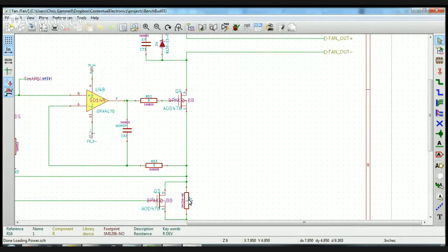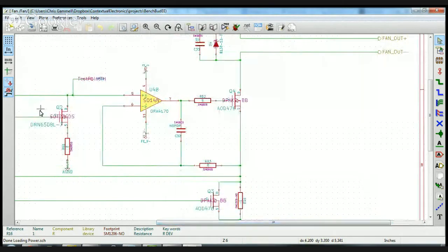So if we went to a 1/4 ohm instead of an ohm, then 4 volts would be 1 amp through here, and then 2 amps. Basically, if we start going lower and lower on the resistor here, we should get more fine control in terms of steps, because then it would be like an 8-to-1 mapping, right? So if this is now 0.125 ohms instead of 1 ohm, we have 4 volts here, that would translate to 1/2 an amp through here, right? So 4 volts, you want to see 4 volts here. Oh no, that is the wrong direction. I'm sorry. Yeah, to get that you need to go up that direction. So we need to go up higher.